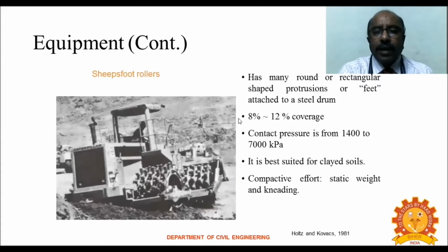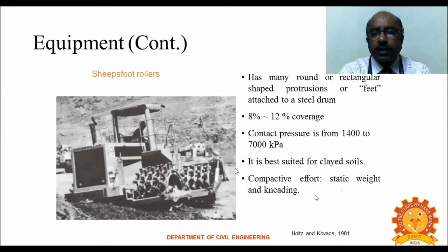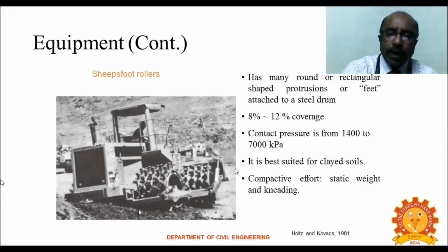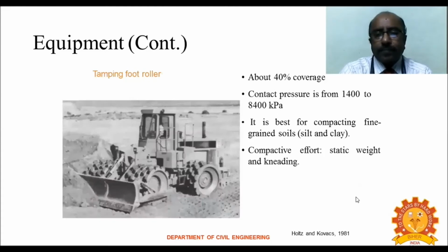But here, the coverage is only 8 to 12%, and the contact pressure is around 1400 to 7000 kilopascal. So this is best suited for clay soil, and here also the compactive effort is static weight. This is a sophisticated roller that is only to be applied in the plant.